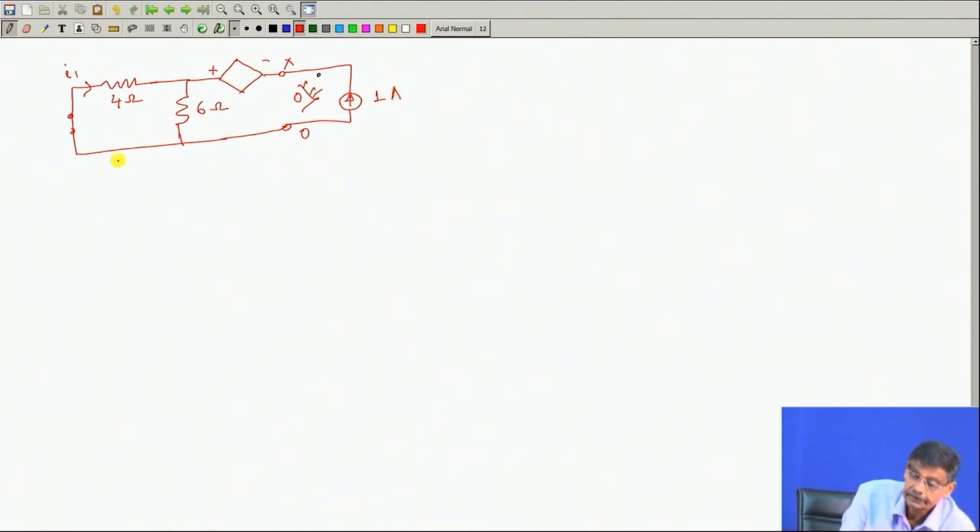I will connect it and then measure the voltage of this network between these 2 points x and O. Then voltage by current will be the impedance of this network between points x and O, that is the whole idea. So, I have connected a current source here, clear.